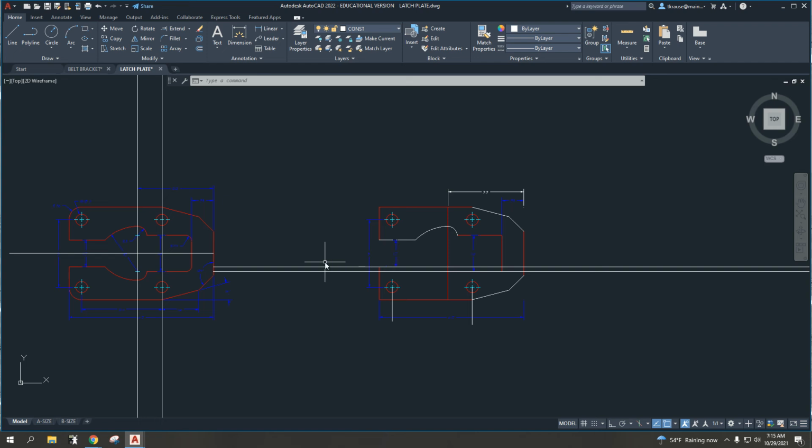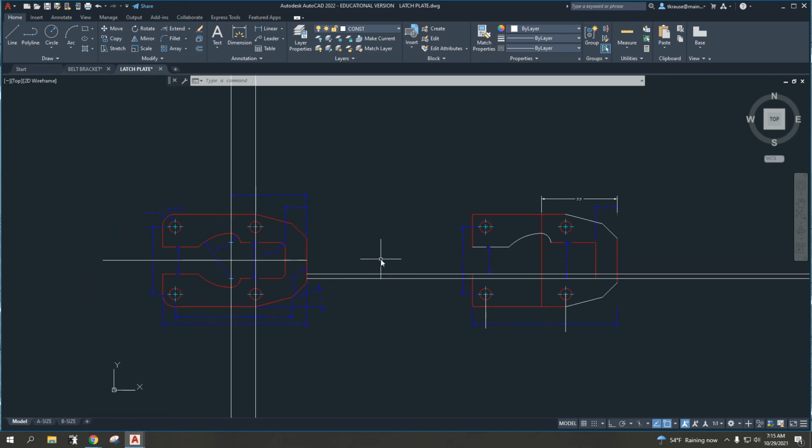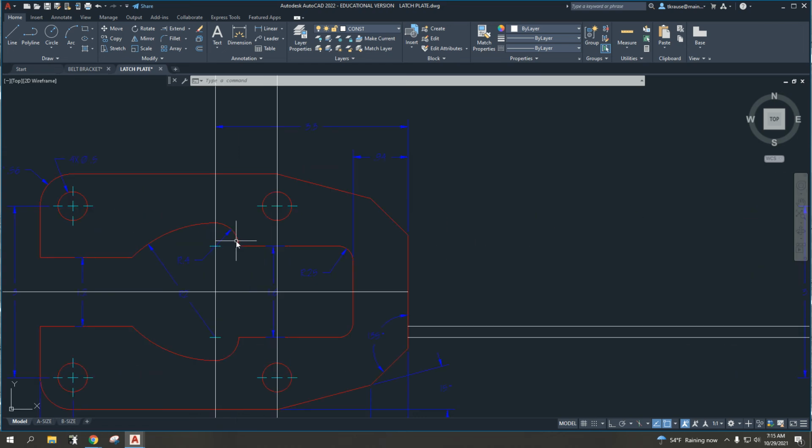Okay, so again, these can get a little confusing with the construction lines. So let's go over to the example and take a look. The center of the small circle, the R4 circle, is aligned with where this line is at. Okay, so you can figure that out again. Take this distance, split it in half, offset from the center. The large radius circle is aligned with the same thing on the opposite corner.